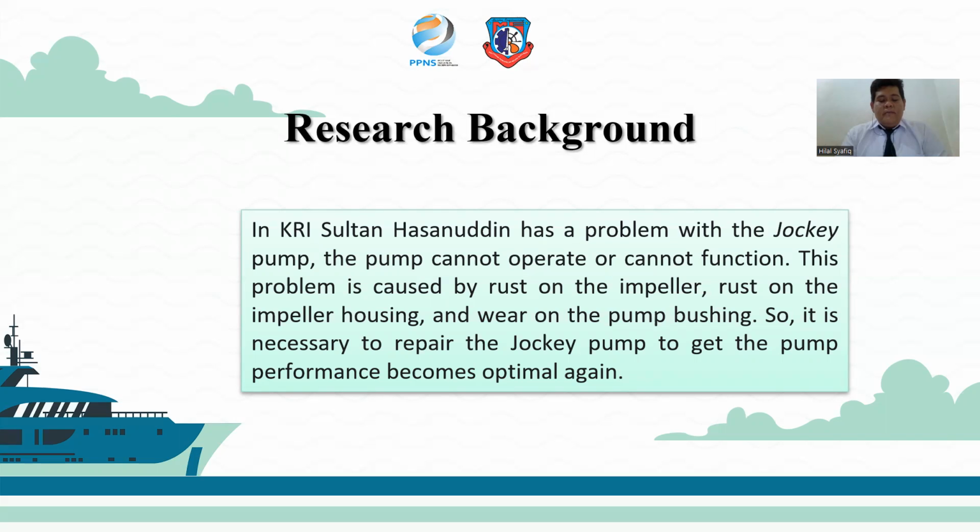This problem is caused by rust on the impeller, rust on the impeller housing, and wear on the pump bushing. So it is necessary to repair the jockey pump to get the pump performance optimal again.